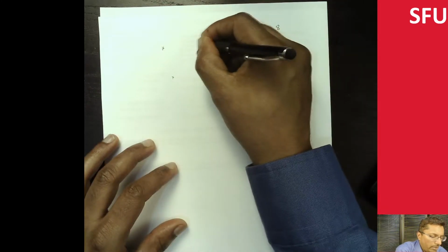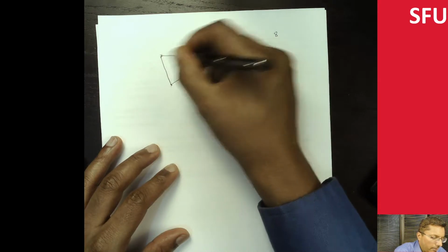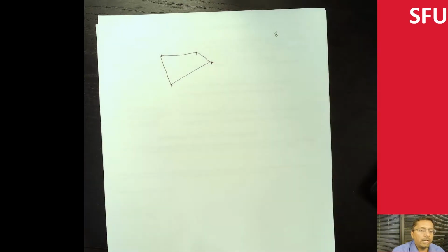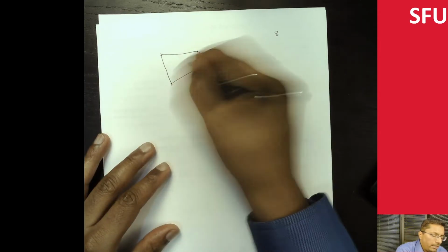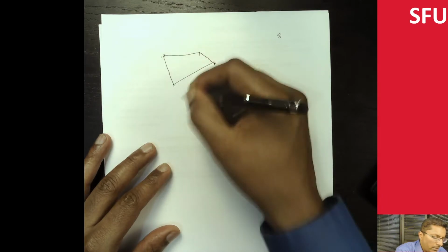And then what that means is, if I draw and then connect these lines, I'm not actually going to get a rectangle. This is actually a quadrilateral. It's just an arbitrary four-sided figure. So what I need to do to get it into a rectangle is I need to make these perpendicular. So the first thing I would do is make this line perpendicular.